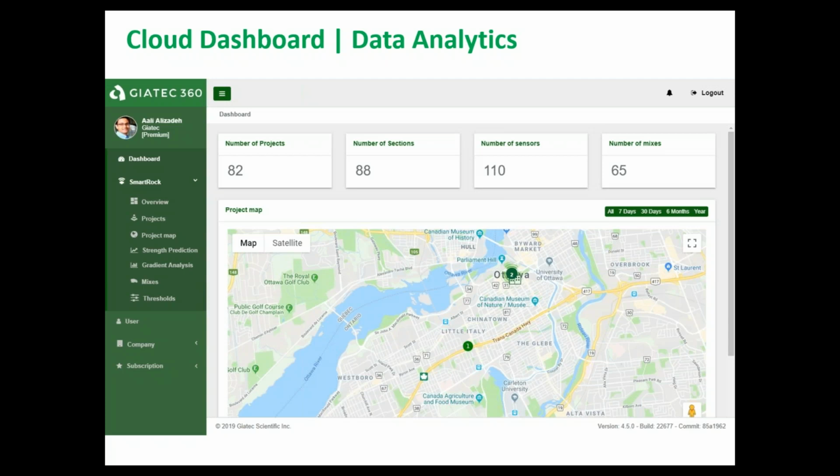based on the future temperature assumption, as you know, using any of the maturity equations, you can calculate the future maturity index. And knowing the future maturity index, you can put it in the same equation and estimate and predict essentially the strength of concrete tomorrow or 2 days from now. And that will give you an idea how things will evolve for better planning in your project.